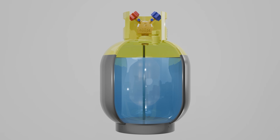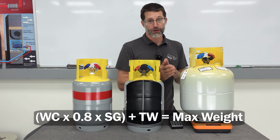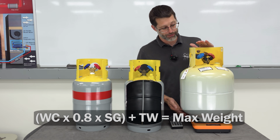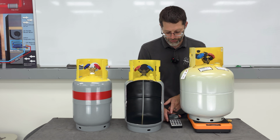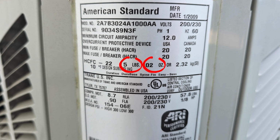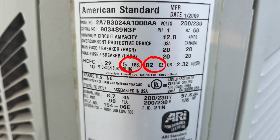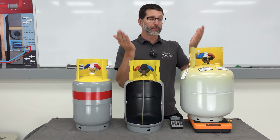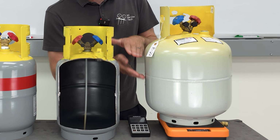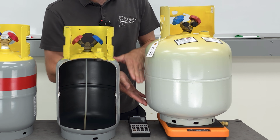After we calculate that, we add the tare weight. That's going to be the max bottle weight that we're allowed to have. And so we would just monitor that as we're recovering refrigerant. And before we recover, we would just check the factory charge in the system. And we'd also look at how long the line set is, just to determine, hey, are we going to overfill the bottle here? So you could kind of fill the bottle to 80% and then switch it out, put another bottle in, and keep recovering.